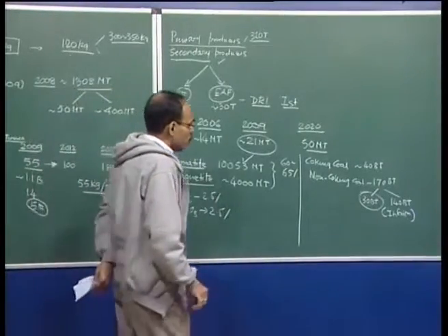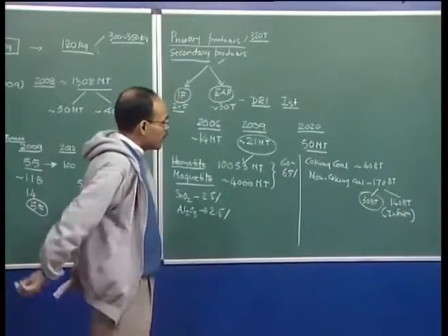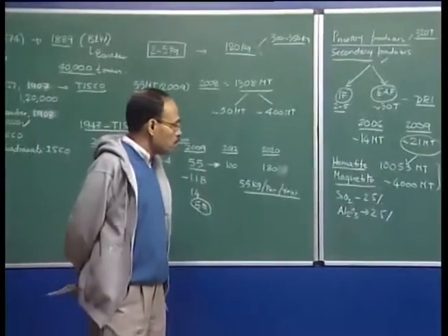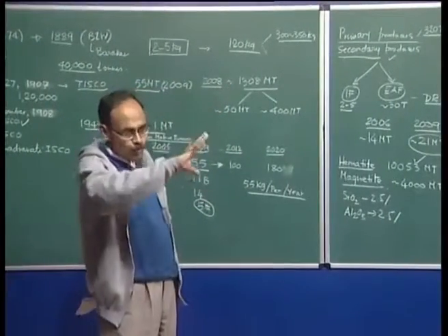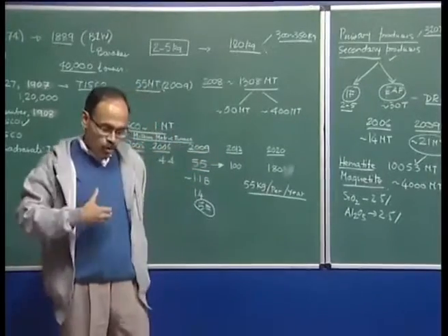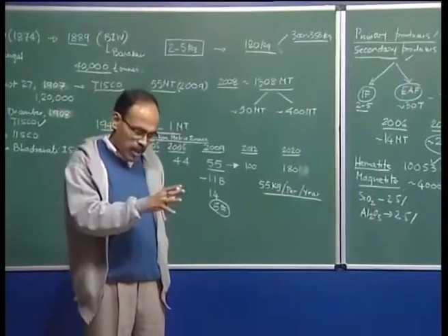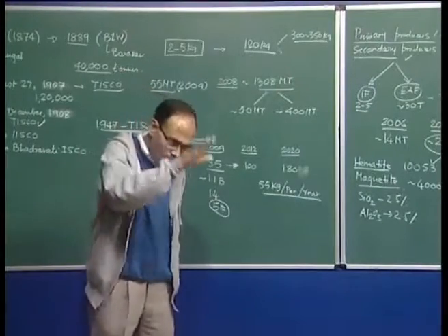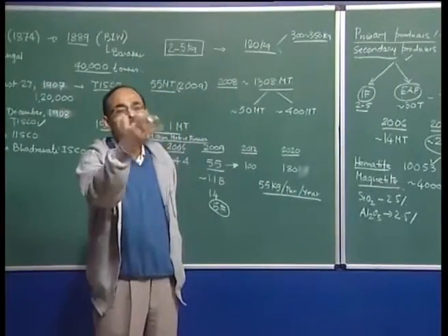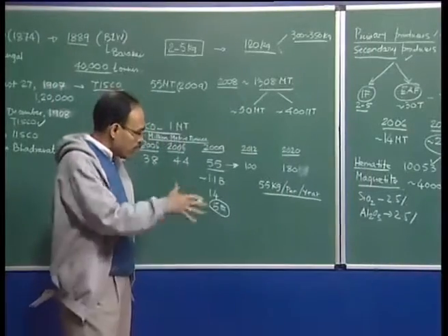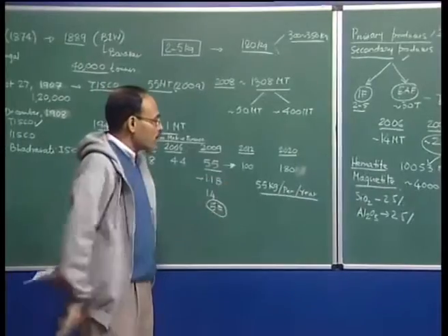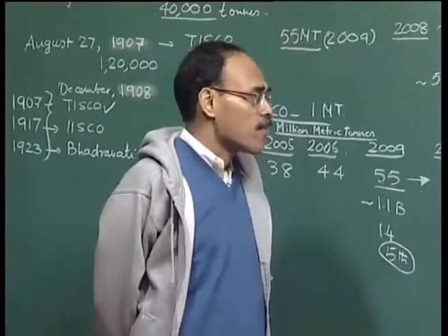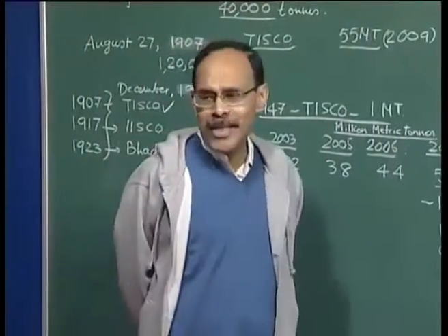Okay. So, the problem with Indian coal, both coking and non-coking, is the high ash, and that is why today you see there are a lot of coal washeries. You have plants which are based on the shore, which function on the blending of the coal. So, we have our coke, which is otherwise fine, but contains a lot of ash, and this coke is mixed with the imported coke, which has a relatively lower amount of ash, and when you blend the two cokes, you get a resultant mixture which has intermediate ash, and which you charge into the blast furnace in order to have good production rate and coke consumption rate in the blast furnace itself. So, there is no dearth of material as far as this is concerned.